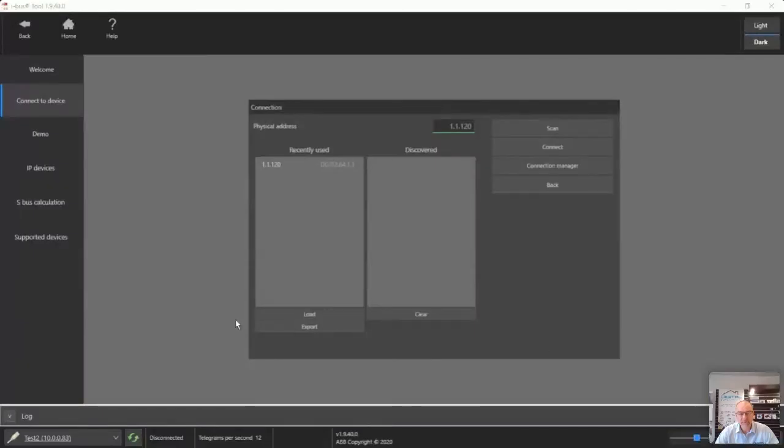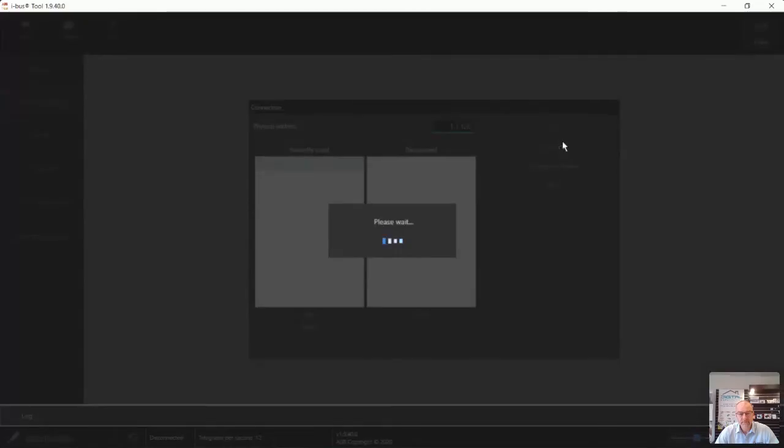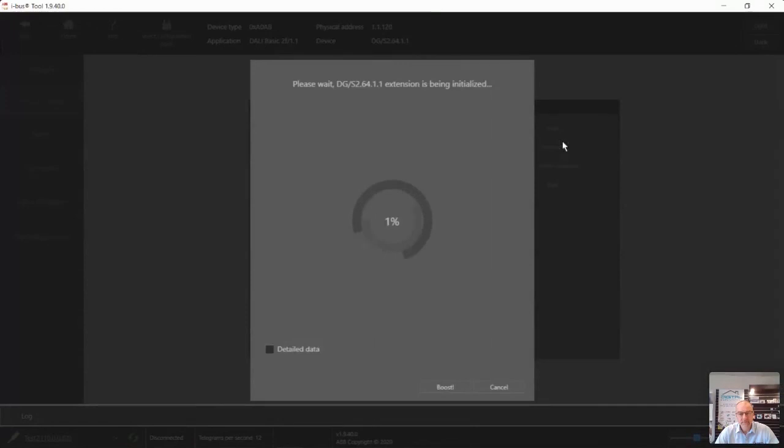Yeah, let me show you again. When I want to DALI address a fitting, like I said, I connect to the device. We pull the information from the device. So when I power up a DALI fitting, the DALI fitting will auto address itself first, because you'll have 50 fittings or whatever online. So usually they're auto addressing enabled, and they will just give themselves an address.